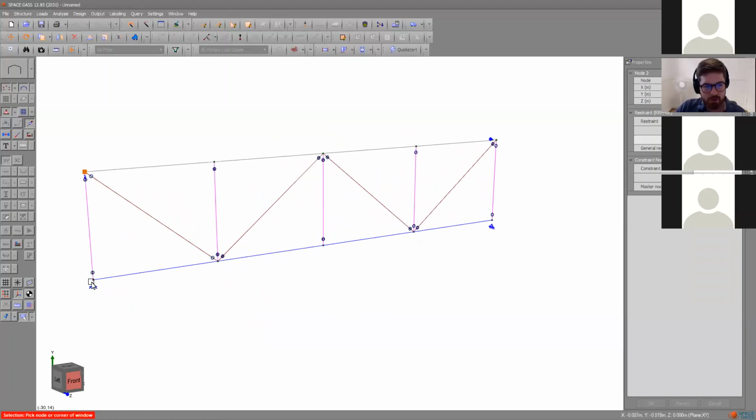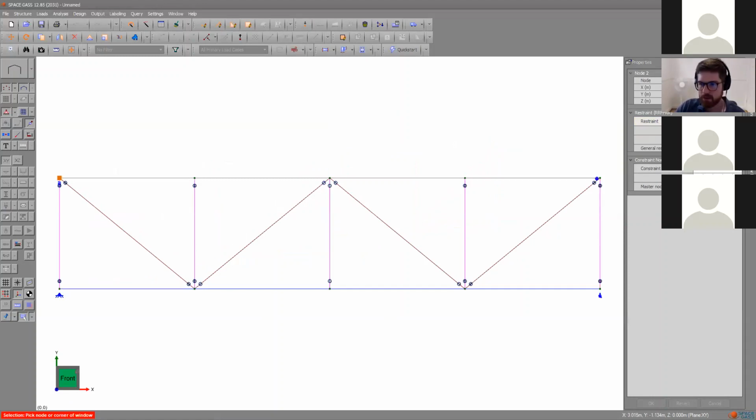So nodes, you apply your standard constraints like you'd expect, but you're operating a 3D system. So you've really got to be mindful of what these letters actually mean. But these first three standard buttons, fixed, pinned, and roller, they will automatically choose the correct restraint for your problem, assuming you're working in 2D, but they'll apply in 3D. So these three really should cover most of your cases, with sometimes needing this additional out-of-plane support to help you operate in 3D.